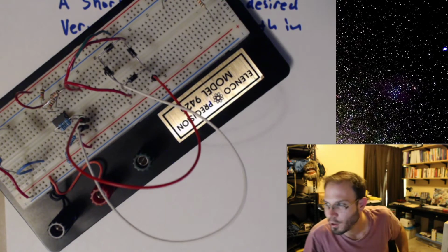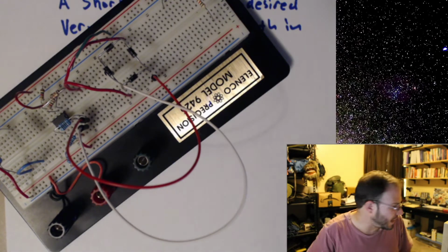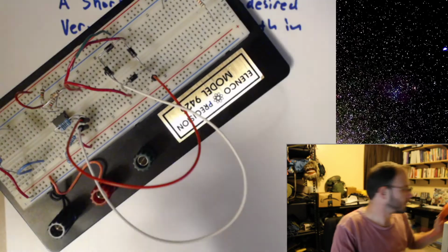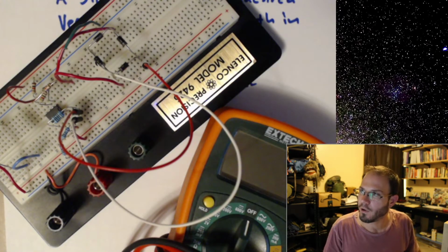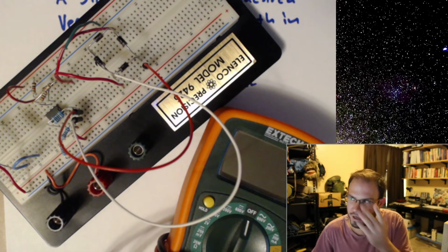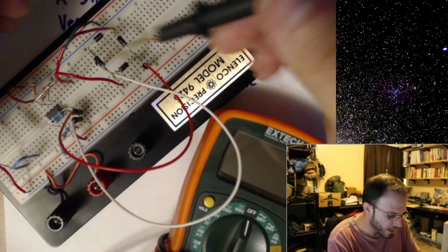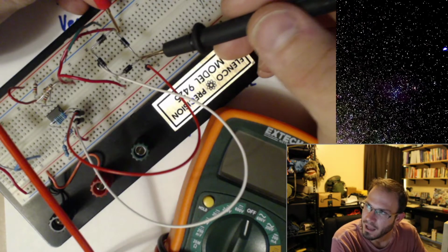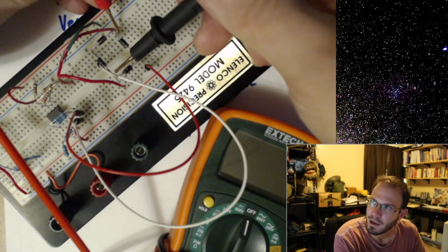Okay, so here's a perfect example of some circuit that I have made on my board. And let's say I'm going to measure some voltage. This is my multimeter. Multimeters are used for measuring voltage, ohms, and current. And to measure, I'm going to have to start probing this, but let's just say I'm not paying attention, and I end up shorting.